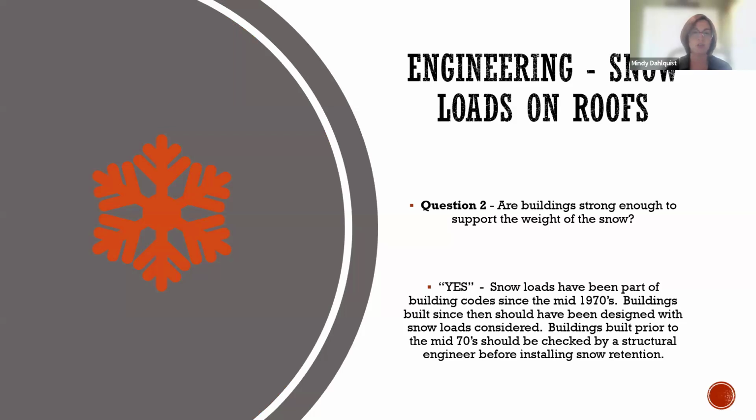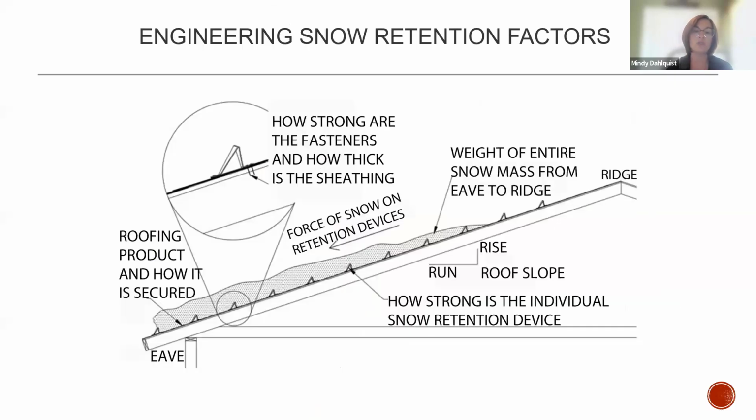of snow retention. So if you've got St. Mary's Church down the road that's doing a full remodel and it's a beautiful building from the 1800s, please do not put snow retention on it prior to having the structure looked at, and make sure that a structural engineer okays that before holding any snow on that roof.